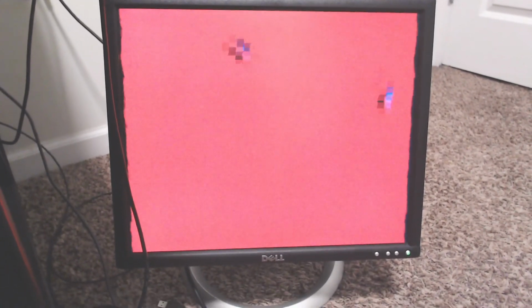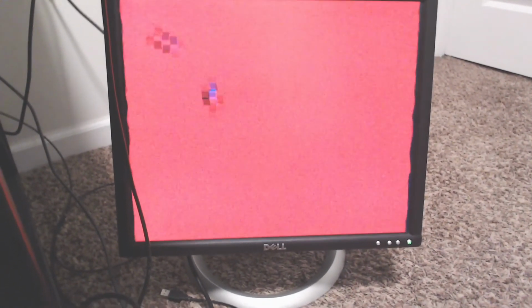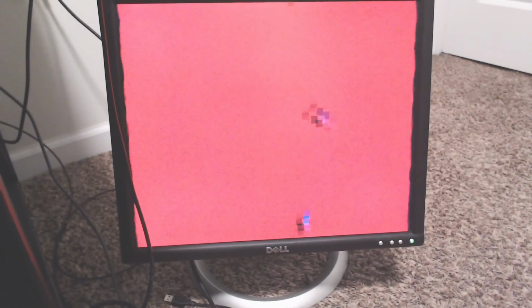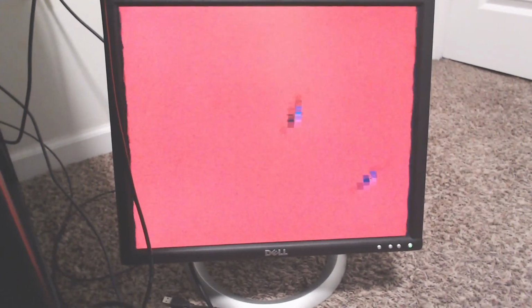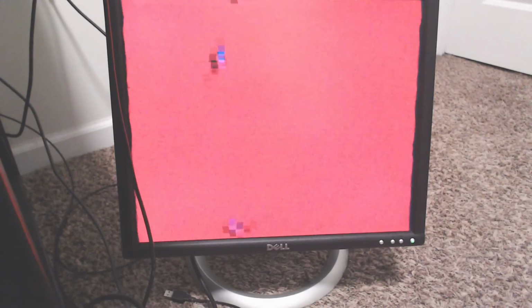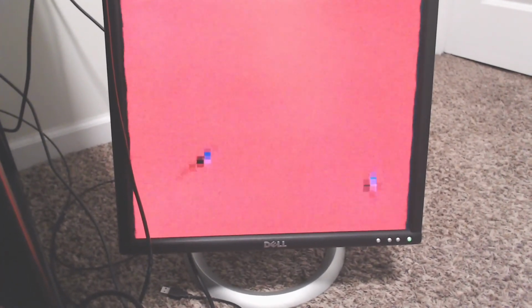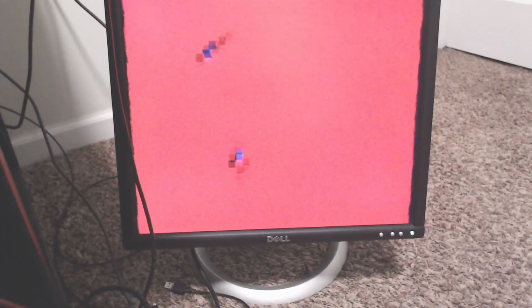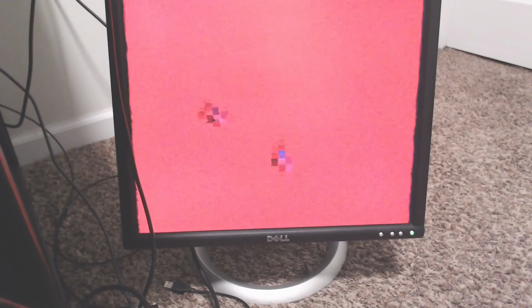And on the side of the screen here, we can see that there's some blurriness or horizontal shaking, and that is because this monitor is defective. I didn't know this when I started working on it because I don't have anything else that outputs VGA. Turns out it's a really old spec, and I've gotten rid of all my hardware that's that old except this recycled monitor. The only way that I can tell that it's broken is because we're in spec on the timing, with a jitter of about 0.01 microseconds. That's all there is to show for this demonstration.